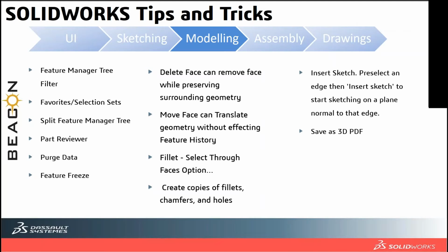Next, by using Control C and Control V, you can just copy and paste. It's not only for fillets, you can do it for chamfers as well as holes. I just showed it for fillets. You can try it at your end for chamfers and holes. The next thing, if you want to create a plane normal to any edge, you need not go to the reference geometry plane and all that. You can just select its edge and say sketch, and a plane normal to that would be created.